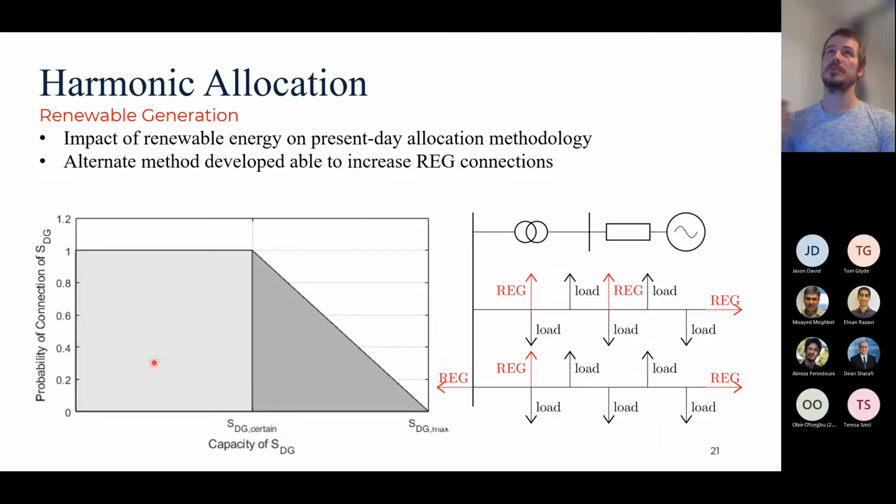There was a paper, and there is going to be a second paper, on ways to manage this. It's all around probability, implementing good planning practices, defining network limits, defining maximums, and taking a probabilistic approach. For example, we know that there can be no more than, let's say, 50 megawatts of generation in this network. Let's say that 25% is almost certain, and the remaining 25% has a sliding scale. Those are really thought starters, not fully developed ideas. They are ideas to apply not a quick fix, but a practical fix while still implementing the Australian standard methodology.